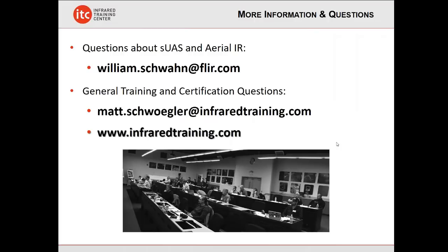There's a lot of great questions, but unfortunately, I just don't think we're going to have the time to get to everyone's here today. Maybe speak about, back to the applications here for a moment. If you're doing roofs or aerial for utilities or whatnot, what are some considerations for the conditions, time of day, things like that for inspecting with aerial infrared? Oh, this is a great question. Of course, depending on the application, for roofing, for example, we have to allow the moisture underneath the membrane to absorb all the solar load and heat up. Of course, then we have to wait for the solar load to leave. So you might be flying a roofing application after dark.